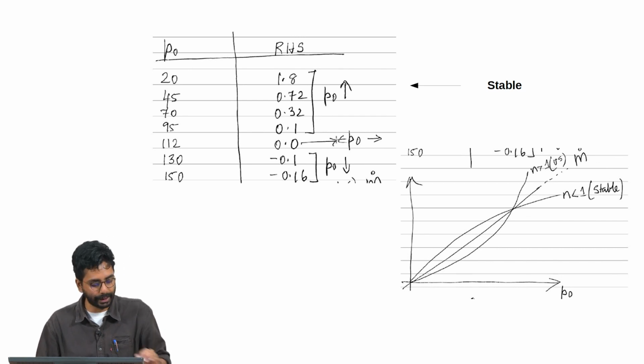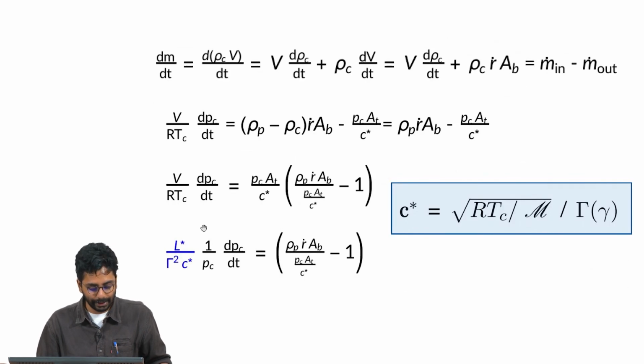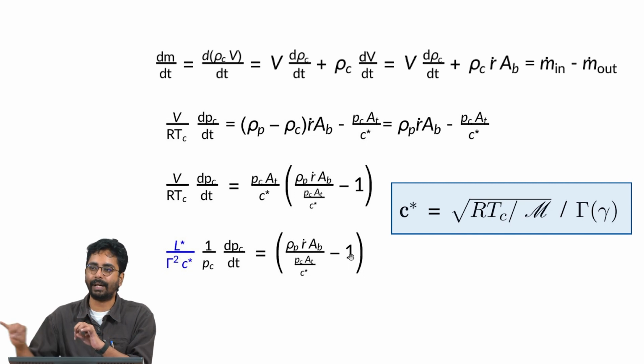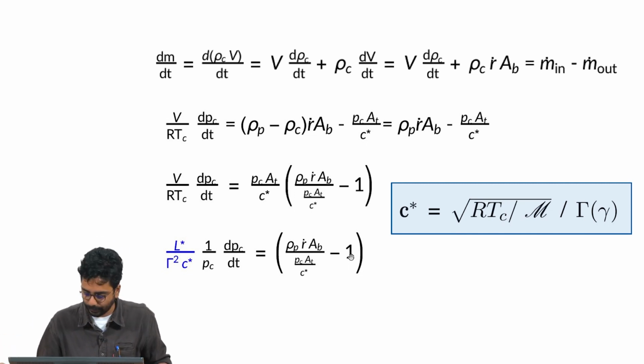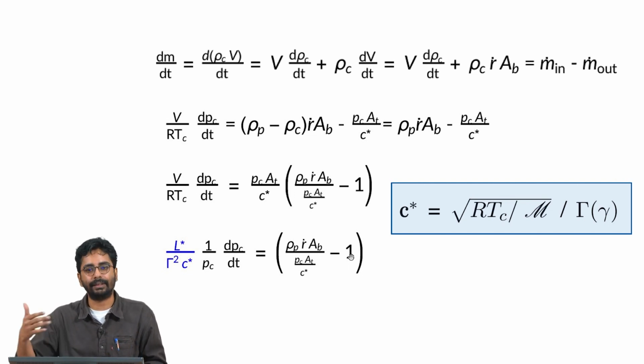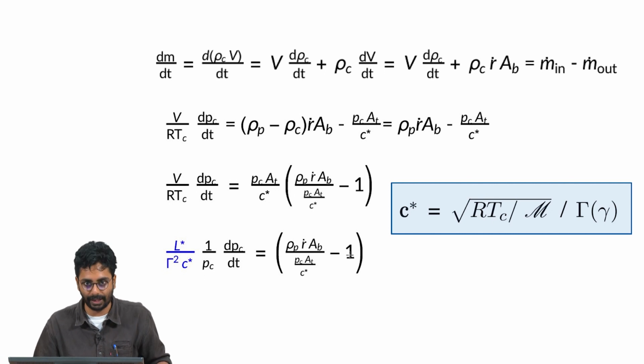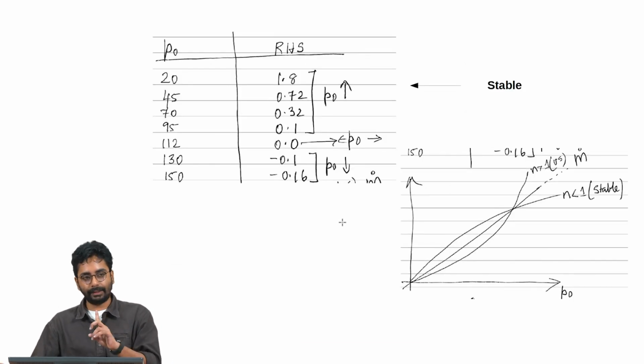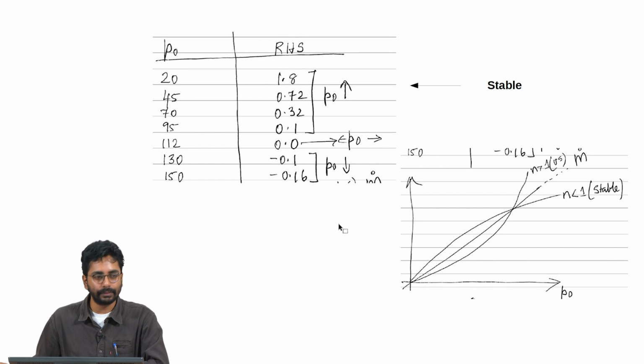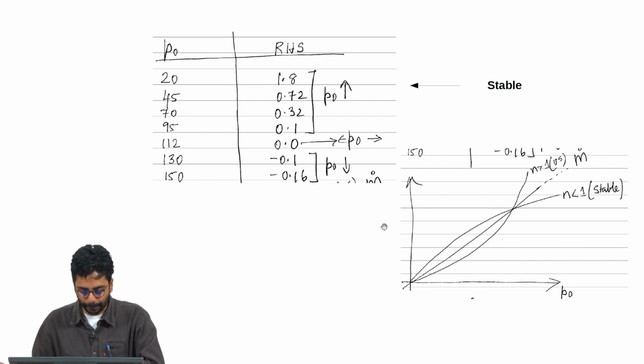If you build a rocket and want to calculate it, the equilibrium pressure is the pressure at which the left hand side is 0. That means the mass generation rate and the mass outflow rate are exactly matched. In reality, it has to be done in a quasi-static fashion, because at different instances of time the burning area will also change, and that is how it is done using ballistic codes when developing solid rockets. But the reason I brought this up is a different and fundamental reason.